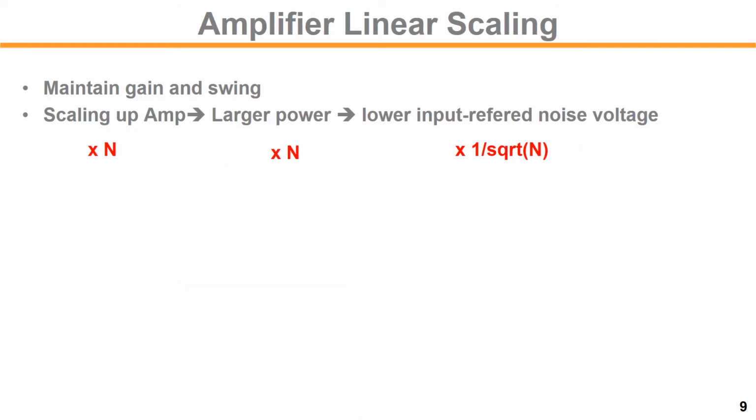So here we will recap the concept of amplifier scaling. It is very important. As you might know, any amplifier can be modeled like a big Gm. So we have the input, Vin, and the current source, and the output impedance Rout, right?